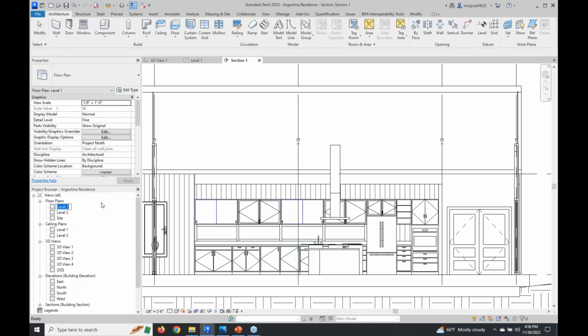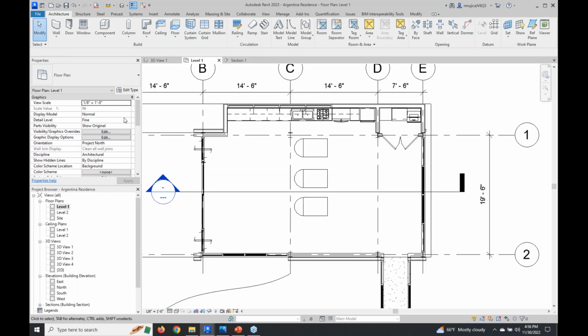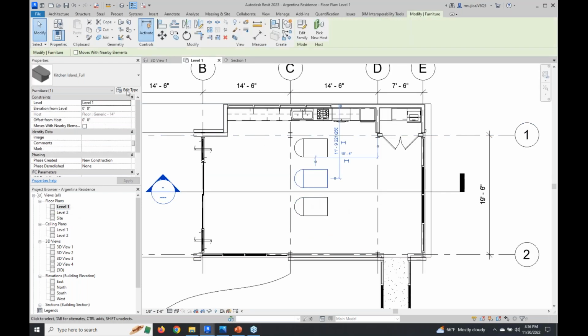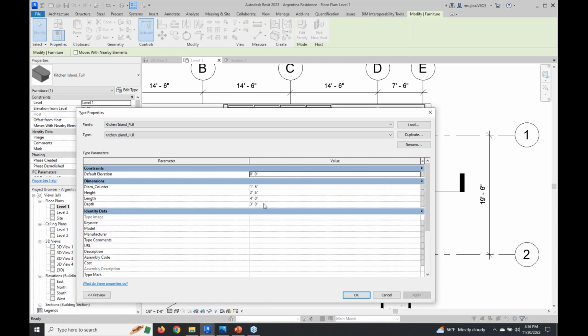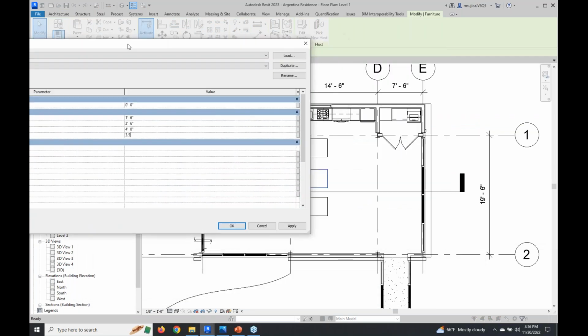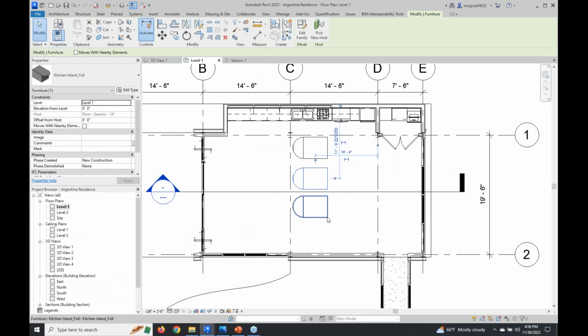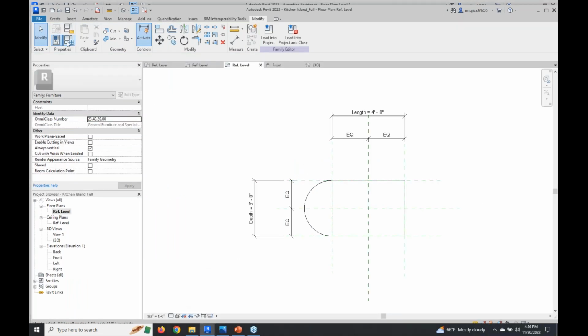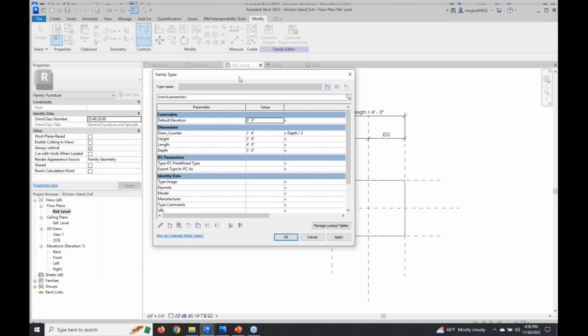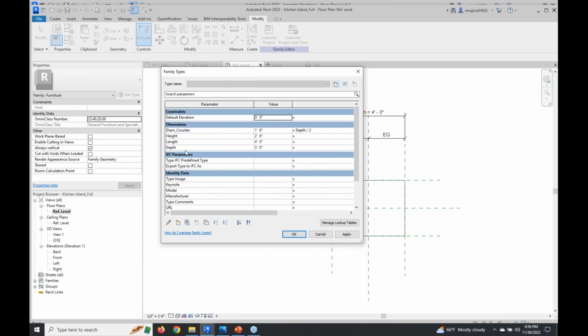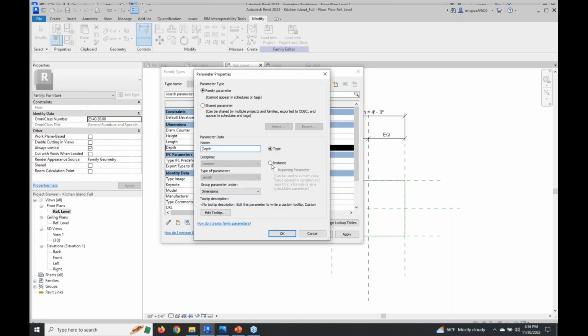On the other hand, system type parameters are universal. So if I now want the depth to be 3.5, you're gonna notice that all of them are gonna react 3.5 here. So how do you wanna do these changes in here? You wanna make probably the depth, edit the guy, instead of type, instance parameter.